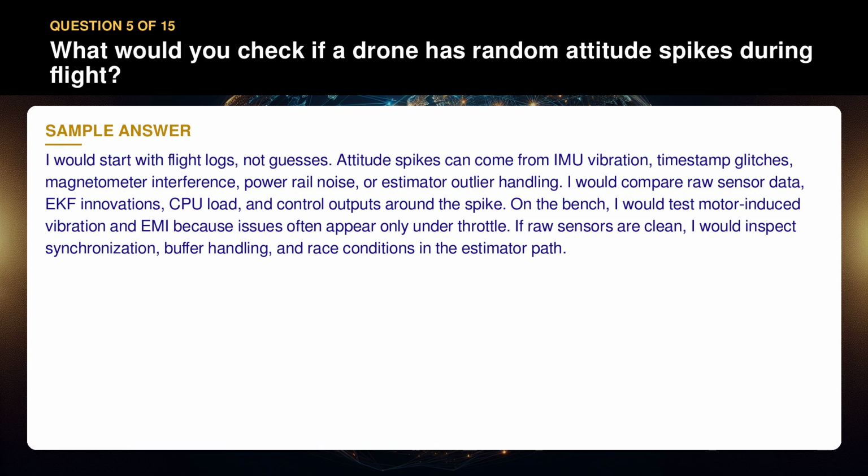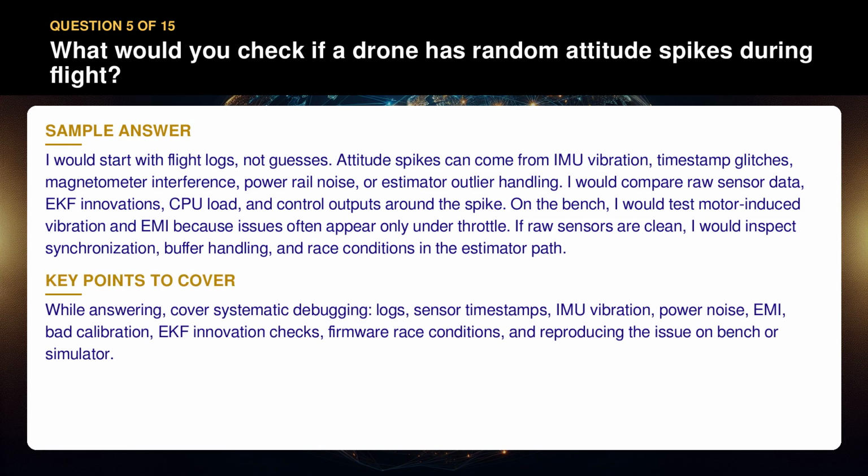On the bench, I would test motor-induced vibration and EMI, because issues often appear only under throttle. If raw sensors are clean, I would inspect synchronization, buffer handling, and race conditions in the estimator path. While answering, cover systematic debugging, logs, sensor timestamps, IMU vibration, power noise, EMI, bad calibration, EKF innovation checks, firmware race conditions, and reproducing the issue on bench or simulator.